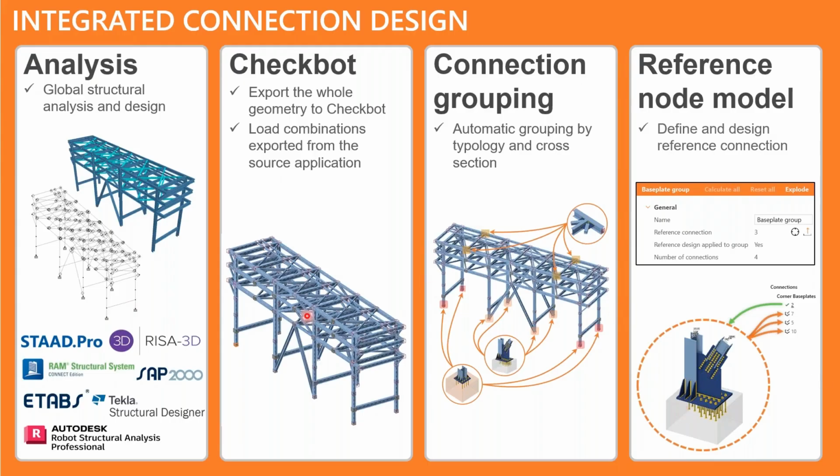From the analysis application that you're using, we can export the structure to Checkbot. The geometry and loads will be imported into Checkbot, and then Checkbot will group the connections by typology and cross sections. Within these groups, a reference connection is defined, like in this case, which will be the parent connection.